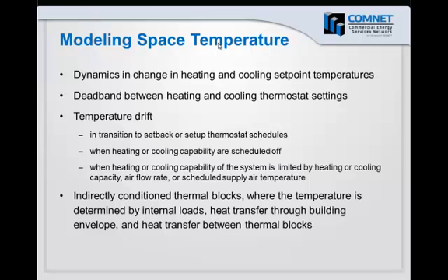And it also needs to be able to model indirectly conditioned thermal blocks. This would be something like a stairwell or maybe a mechanical room that has no direct supply of heating or cooling, but instead it's basically heated and cooled by heat transfer from adjacent zones or by air transport between adjacent zones.